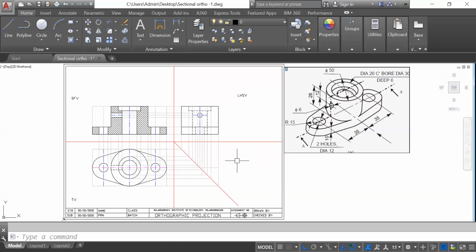And when I take a cut, or actually if I take a cut by a saw, then the unpainted area, we have to hatch it. So if you imagine like this, then your section will not be wrong. So do imagination likewise. You will get the correct section lines at the correct location. The only thing is that if a rib is present in the object, we have to omit that region for the section. Getting?